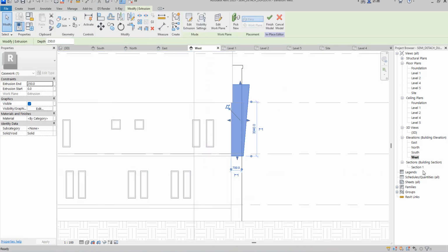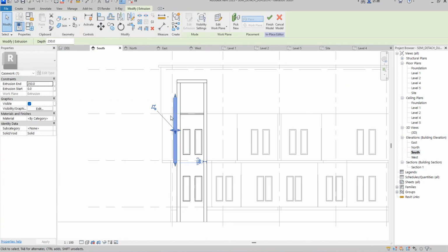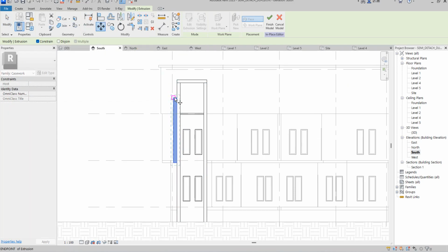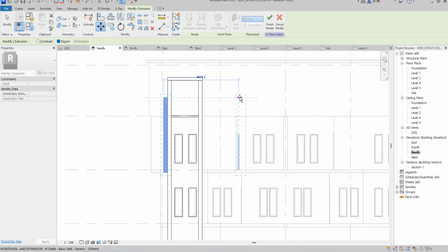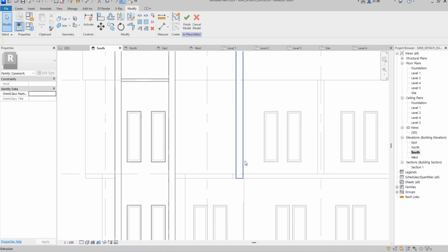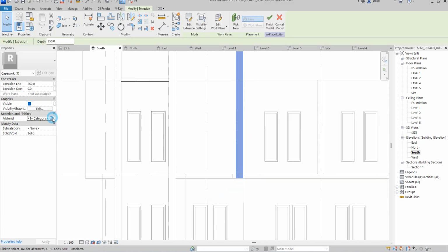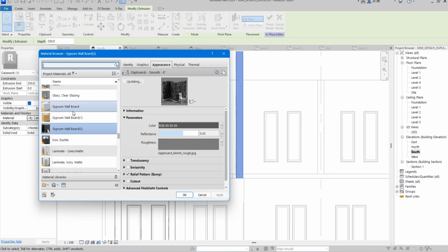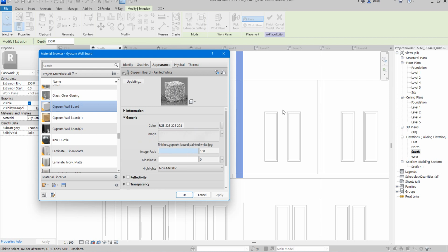So click finish. Then go to start elevation. From there, I will just move. Click move and then disjoint. Remove the constraint and disjoint it so that you'll be able to flow. So I'm placing it at this side. Good. So I think my category is the same, I'm still using the same gypsum board.